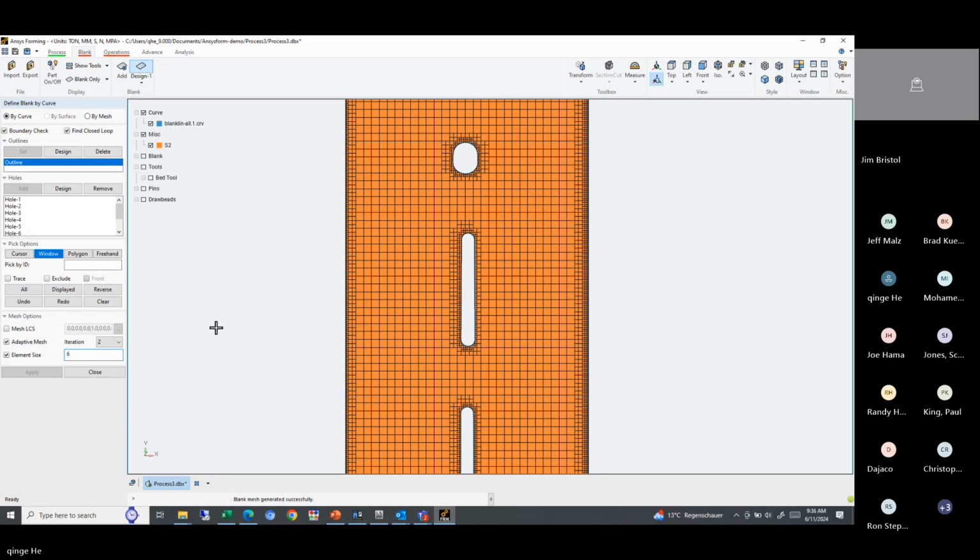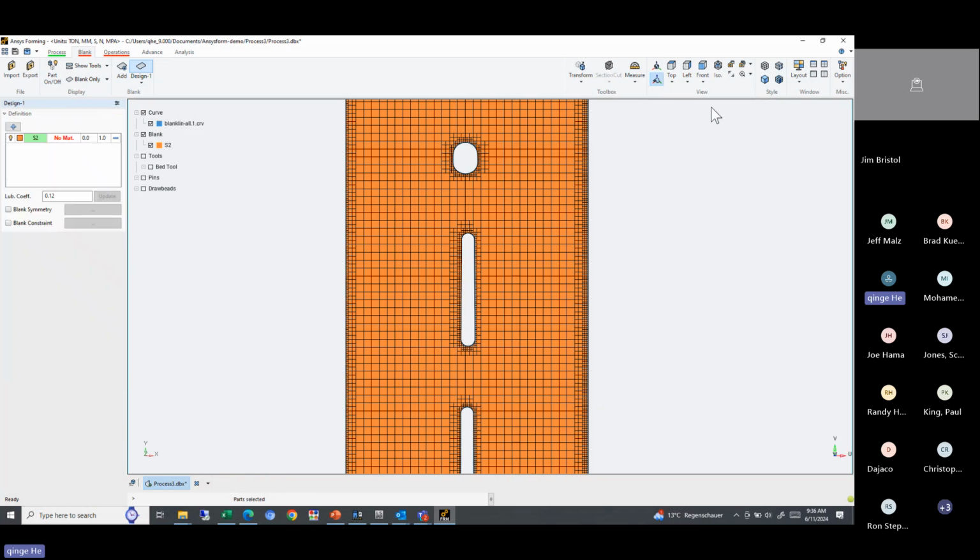There. Okay, and then you can have small mesh cover those detail areas and then large mesh in the flat area. The reason we do that is the speed. You can have the simulation faster if you have a larger mesh.